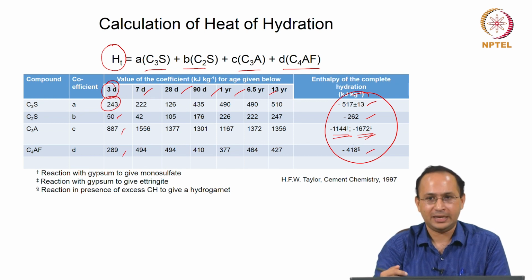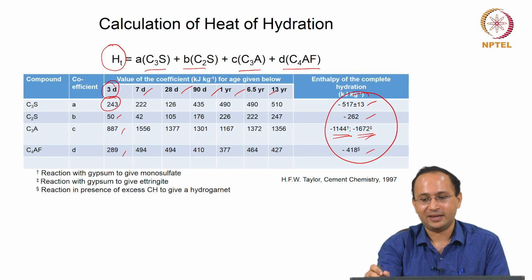We are not going into detail, but in cement chemistry or any other class you must have learned the reactions, right. C3S when reacts with water gives you CSH, calcium silicate hydrate. Same thing C2S. C3A reacts with calcium sulfate or gypsum to give you AFt or ettringite, right. Then AFt converts to AFm, monosulfate, right. So it is good to know these enthalpies for pure phases, because then if you know how much of it is, you will be able to calculate.